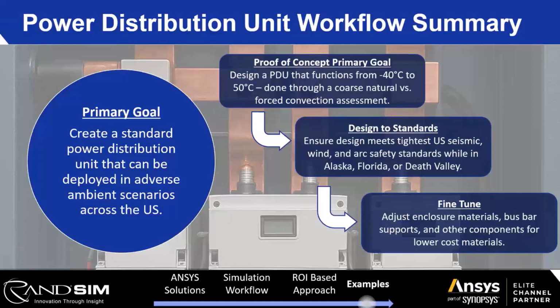So it's taking the simulation workflow and applying it as you would any design workflow, starting very simple and growing on an item to make sure that you're not trying to tackle everything all at once, right? If we jumped in right away and we tried to say, hey, we have this concept for a power distribution unit and we want to see if we can change the chassis from stainless steel to aluminum, we've missed 50 questions that we need to answer before we're at that point. And if it doesn't work changing it to aluminum, we might be back at step one because we didn't do a proper assessment in that simulation workflow.